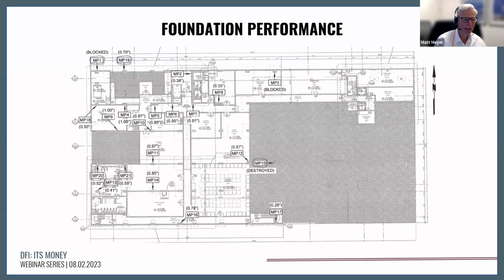And remember, we're talking about elevation minus 40 compared to elevation minus 85. And the settlements are less than 1 inch throughout the entire tower structure. And remember, I mentioned that we deemed that deep compressible subsurface material inconsequential relative to these reduced height structures. Indeed, that was the case as we measured the garage structures for movement as well.